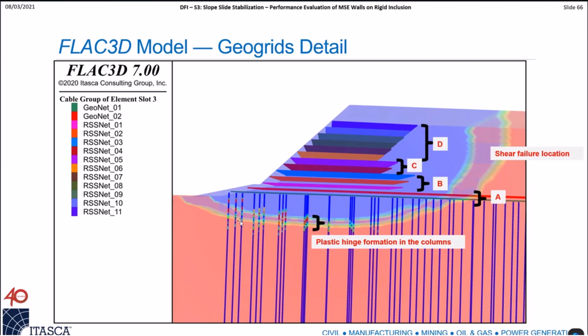While if you plug in, for example, a limit equilibrium and you do just a force analysis, considering the full mobilization of the shear force of this column, you might get a satisfactory number. But there are two problems with that approach. One, the shear capacity of the columns neglects, most of the time, the bending. So the bending brings the columns to failure first, then the shear. And second, the strain compatibility in this system is totally neglected when you go with a limit equilibrium type of